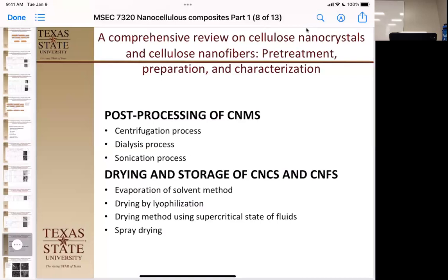In spray drying, you're literally taking a solution of it and blowing it up or down into a heated area and then having it evaporate before your solid touches the ground. And your solid is dry when it hits the ground, and then you just sweep it up. That's your material, and it makes a nicely dispersed material.